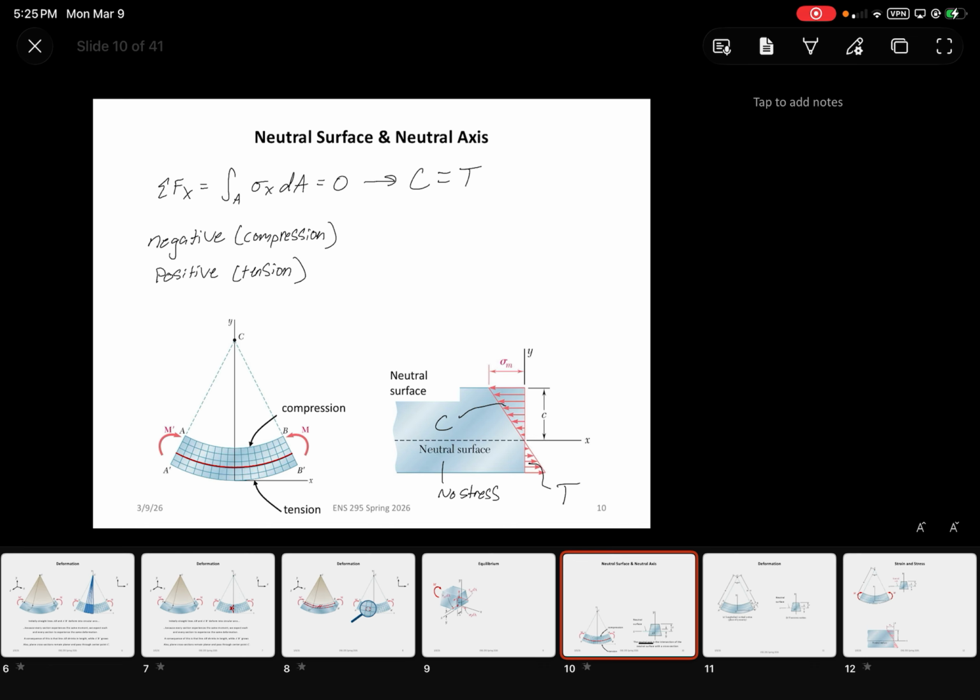That's the neutral axis. If you were dealing with a rectangular shape, the centroid is dead center in the middle. That's basically the location of the neutral axis. There's a reason why you did that in statics, and that's because it is a very critical point in determining how the stresses vary, because that is a known point of what the stress is.